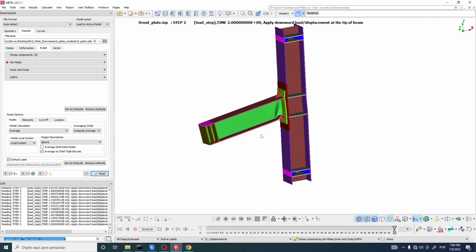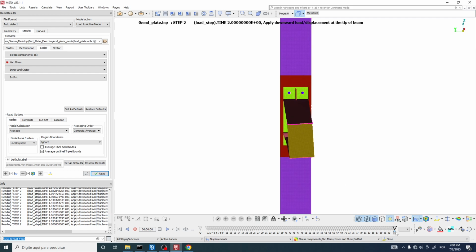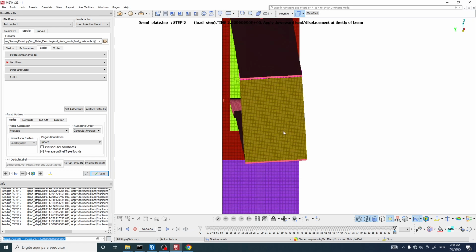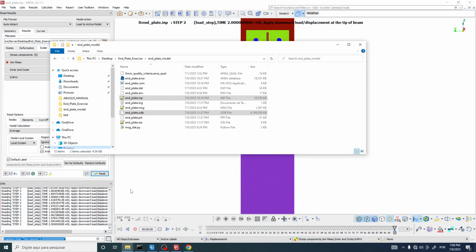There is another thing that I wanted to show. Let's press F1, F2. Yeah, F2. You see that while we have this displacement occurring, since we have just applied this downward displacement without any kind of restriction, we also have this displacement to the right occurring. We could have fixed this displacement in the y direction so that we don't have this happening. And maybe this is a good idea, you know, because in the experiment, we have this kind of restriction.